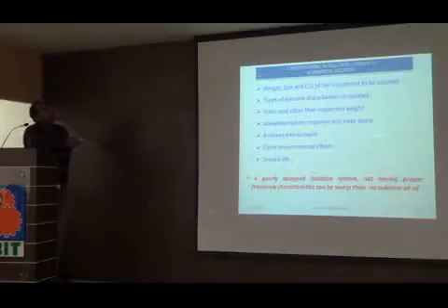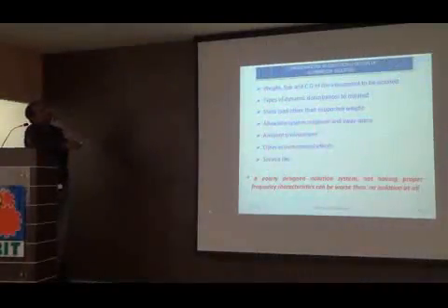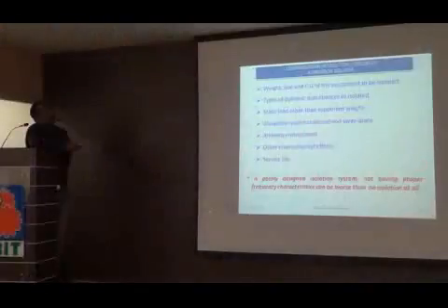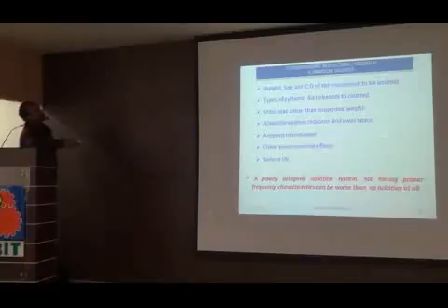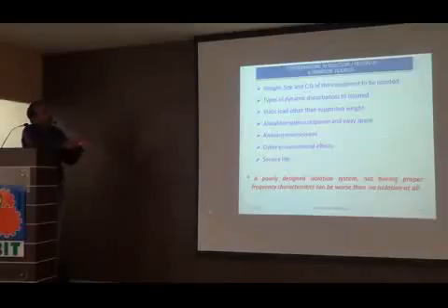Another consideration when you select an isolator is that you should be very careful with the weight, size, and CG of the equipment to be isolated. You should know what the types of dynamic disturbances to be isolated are. You should know the static load of the supported weight, and also the static loading of the isolator. You should know the space allowed, meaning when you load a system and when you are vibrating, the isolator is going to have some space motion. The system should not have any obstructions in that zone, otherwise it is going to have a lot of heat there.